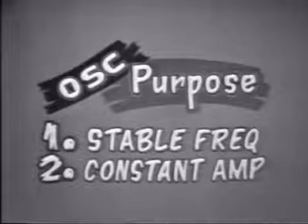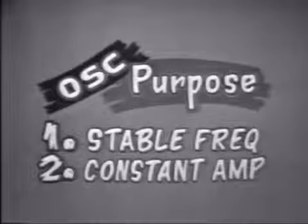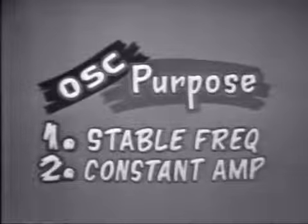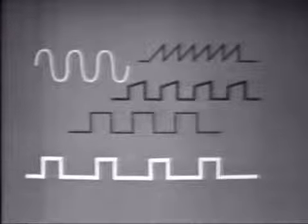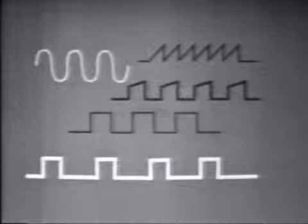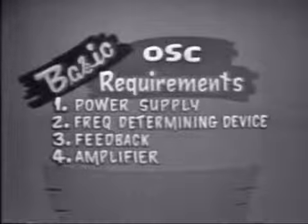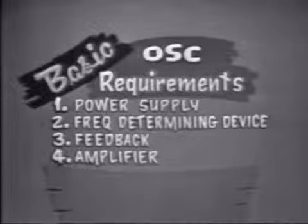First, any oscillator should develop a stable frequency and a signal of constant amplitude. Now, be sure you understand that this statement applies to all oscillators, the LC or any sine wave oscillator, as well as the sawtooth, square, rectangular, or trapezoidal oscillators. All of them should generate constant amplitude and frequency. Now, here's a list of the basic requirements that also applies to all oscillators.